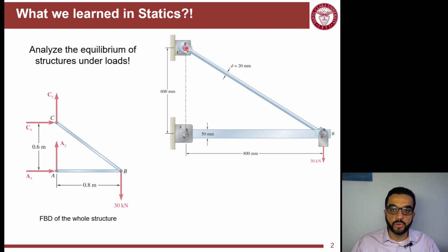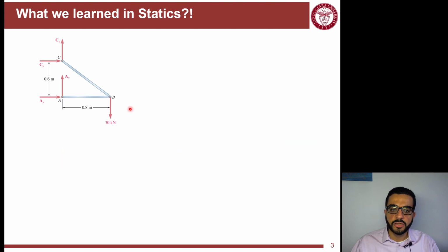So we have here two pins at A and C, and then we have the load. This is a very basic free body diagram. It doesn't use knowledge that we had, which is two force members, AB and CB. I can recognize these two force members because there is no load along their length and they are pinned at both ends. But here I'm trying to use the very basic free body diagram to model the structure. Once you put the reactions in the free body diagram, you can actually now start analyzing parts of it.